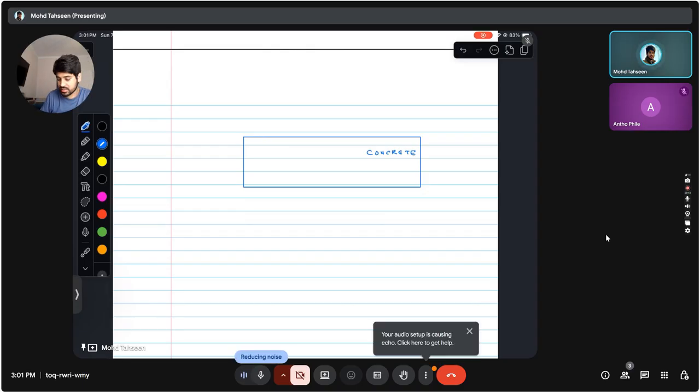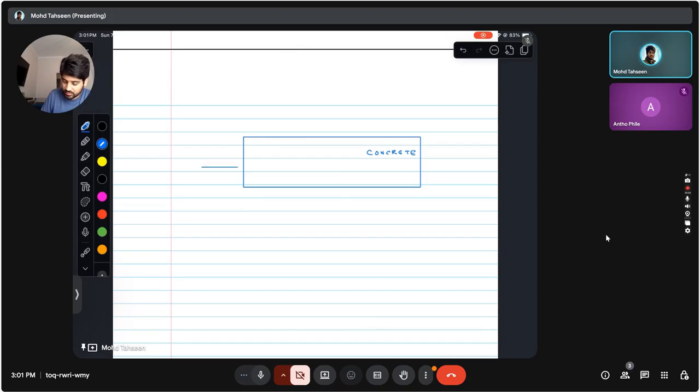Concrete is designed in such a way that it is extremely durable under compression, right? So if you compress it, it can take a high amount of compressive loads. That's why the pillars of our houses are made of concrete, right? And there is a vertical load due to, let's say, the floor or a roof. All the load of a roof applies a compressive load on our concrete walls as well as pillars. But concrete is weak in tension, right? So concrete is weak in tension.